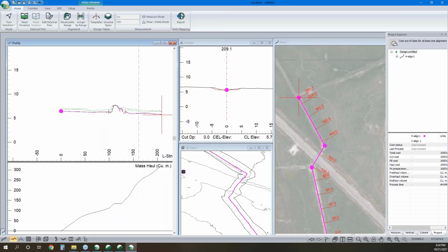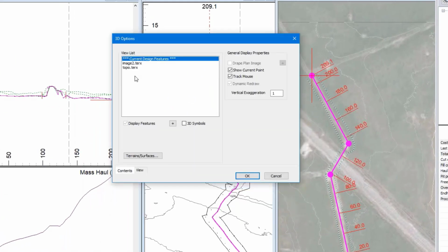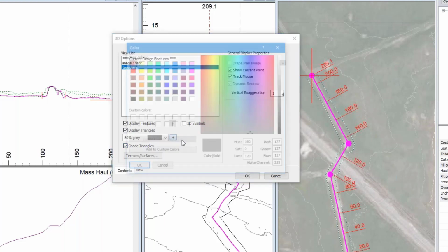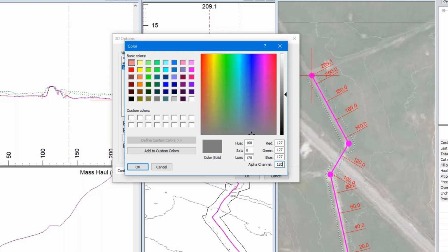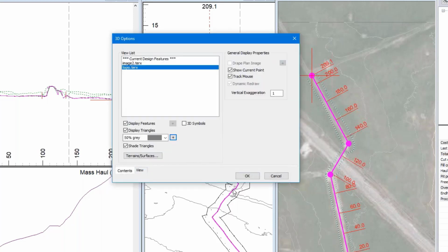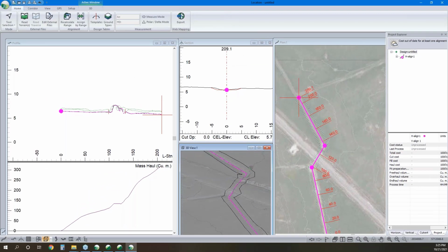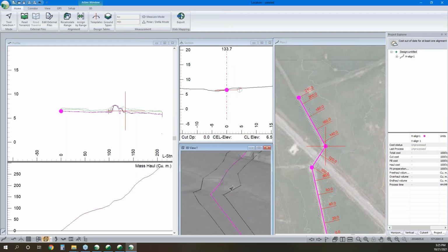So we've got that. Before I get going too far here, I'm going to just change a couple settings in my 3D view. I'm just making it so I can see that original ground as a surface. And there we are. And I'm going to use that. It makes it easier to line up where I want to put things. And for this, it is a fictional project, but I'm going to assume I'm going to remove that culvert and roadway just because they're stacked right on top of each other, and we could just put that culvert over here and have less flow go through it.